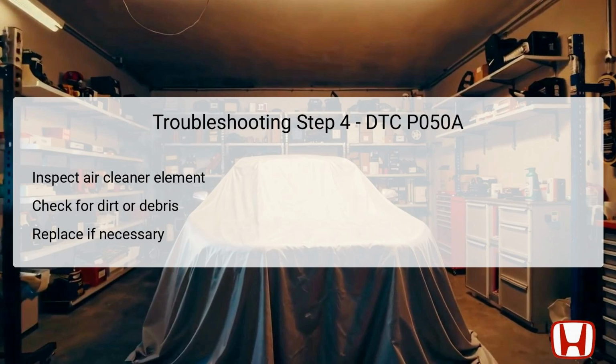A clean air filter is fundamental for ensuring that the engine receives the correct amount of air required for efficient combustion, especially relevant during cold starts. If the air cleaner element is clean, then proceed with further diagnostics.